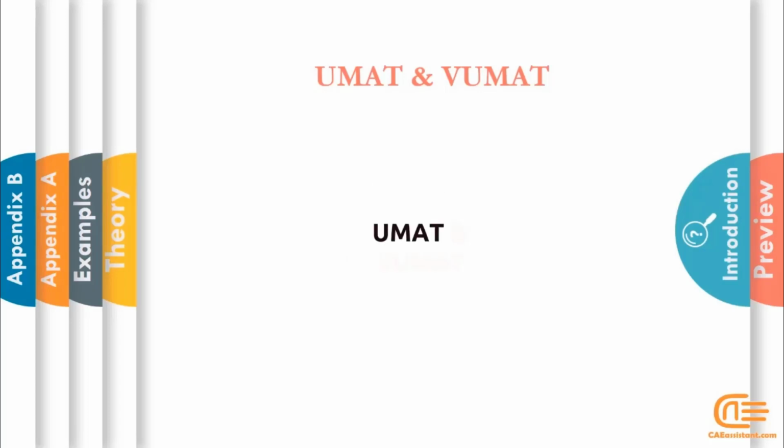But UMAT is the most famous subroutine for defining material behaviors. This is because UMAT and VUMAT have a very high ability to define various behaviors such as different types of elasticity, plasticity, damage, and many other properties. Well, now let's get to know UMAT more.